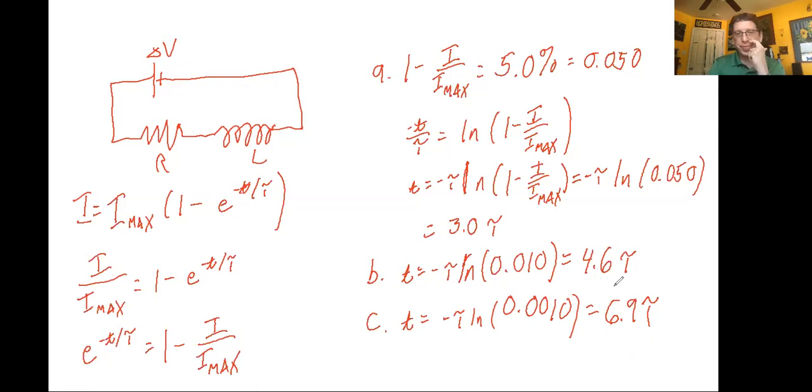So it's under fairly rare circumstances that you can observe in real time the building up of current in an RL circuit. And usually you need an oscilloscope or some sort of assistance that works on very small time scales in order to see the voltage building up, or the current building up over a very small period of time.